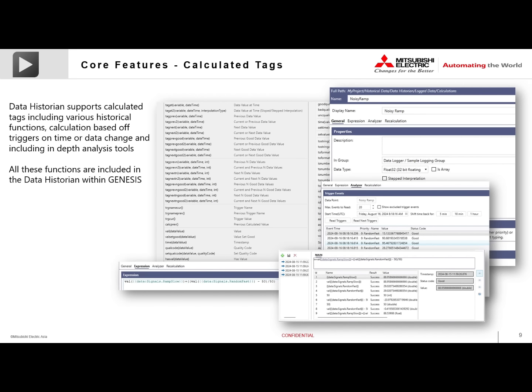So over here, you see that these are the built-in calculation functions which are available. For example, when we log data every 5 minutes, you can predefine the trigger link to calculate hourly totalization or daily or weekly or monthly totalization of values. You do not need to wait when the customer or the operator opens up the graphic page. They don't need to wait for the totalized value on the fly, as it will be already pre-calculated.